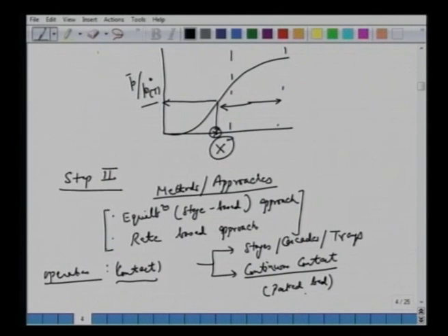Now again try to understand this and try to recall that our approaches are different and the real process is different, right? In principle one can apply either of the two approaches in any of those arrangements, but for our convenience, if we have trays like in a distillation column, one would like to apply this equilibrium based approach. If you have a continuous packed bed like a packing, or you have absorption, one should in principle apply the rate based approach. For simplicity, of course, one can always have the concept of theoretical stages, theoretical plates, height or distance between the two plates. One can do this, right? But for our convenience, if you see the real system in which we have the trays, we can think of equilibrium approaches. Two leaving streams are in equilibrium.